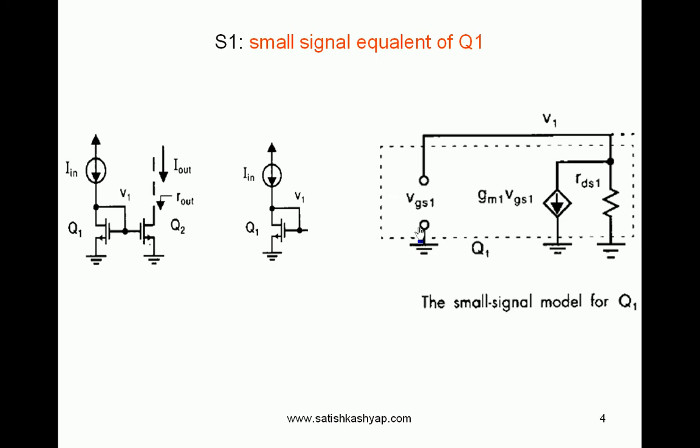Gate current is 0 is nothing but input current is 0. Input current is 0 is nothing but input impedance is infinite. Input impedance is infinite means input side is open circuit, so that only voltage exists but no currents are going to be existing at input side. So input side is nothing but gate source side. So this is VGS1. Input side is open circuit since no gate current flows.